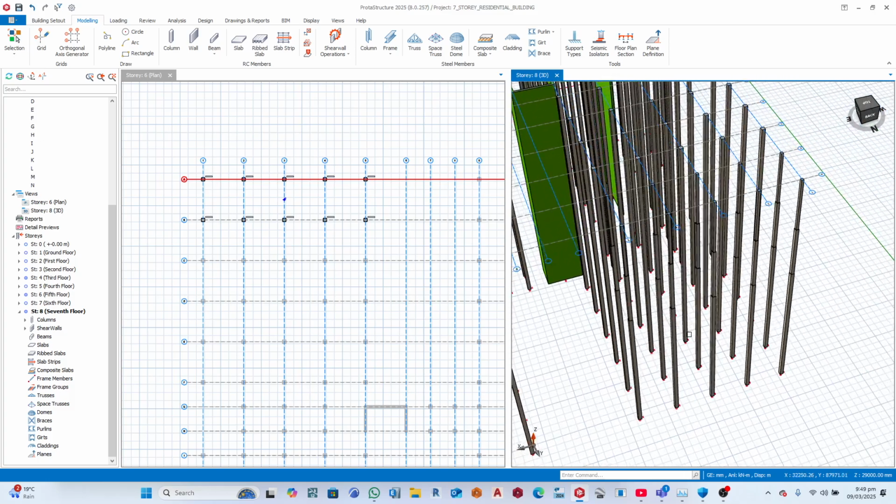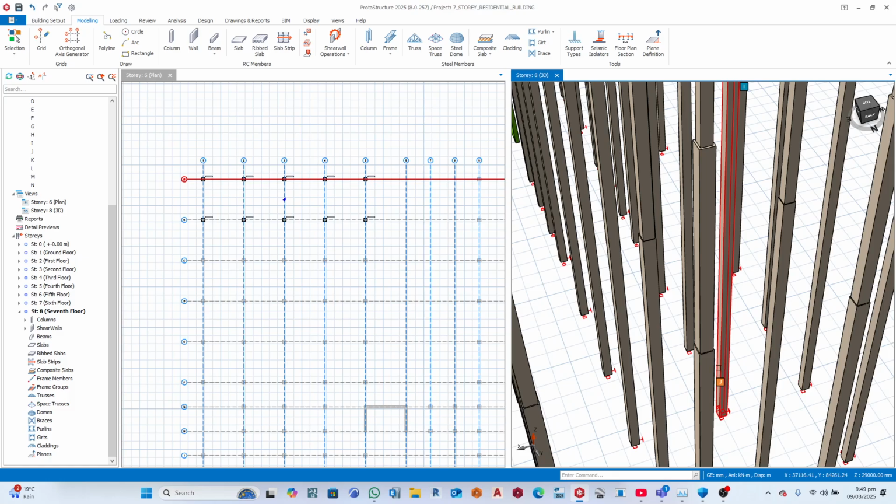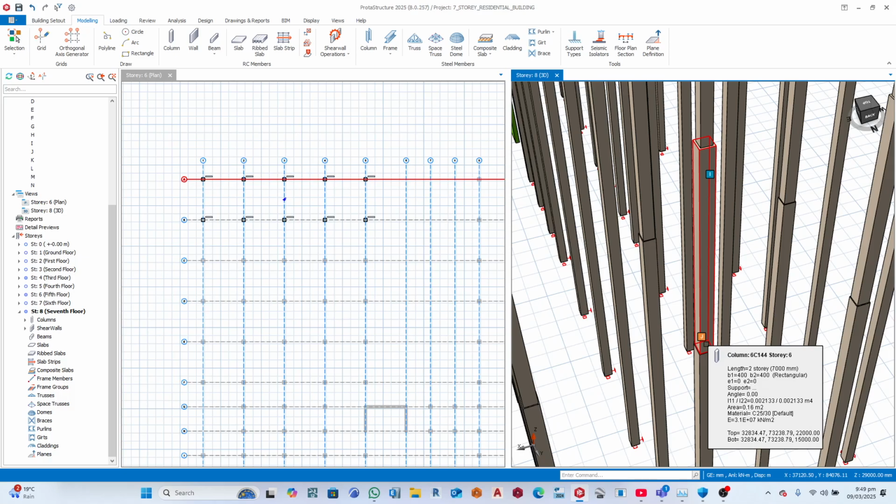So now, how is the load at the King's Hospital transmitted? At the King's Hospital, you can have column sizes change. They are changing. Why? Because as you are going up, you're going to be having less. You know how the column behaves. The axial force that is on top, on the 8th floor, after which is the roof floor, brings the axial load on the column.